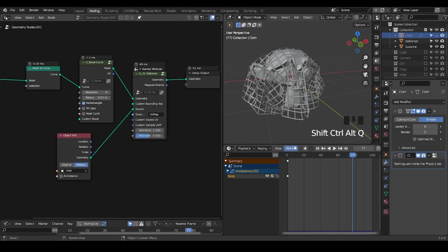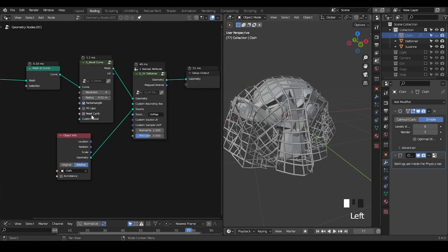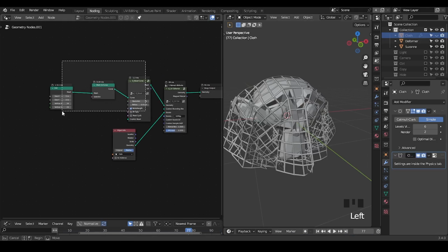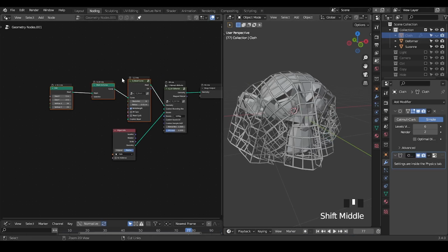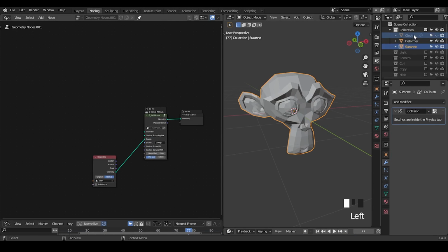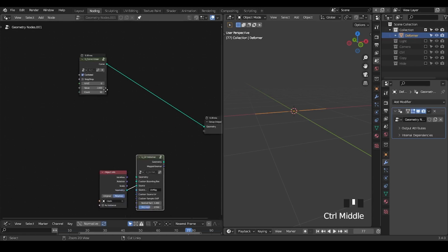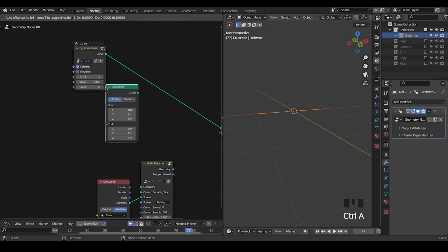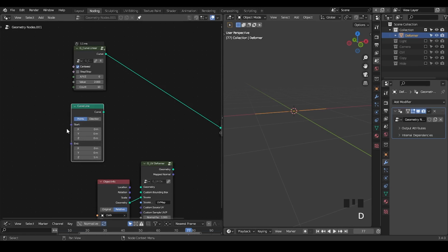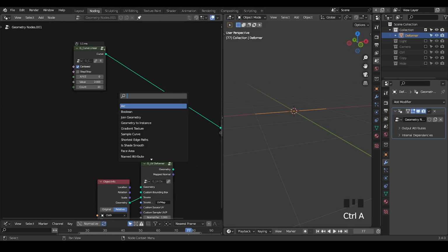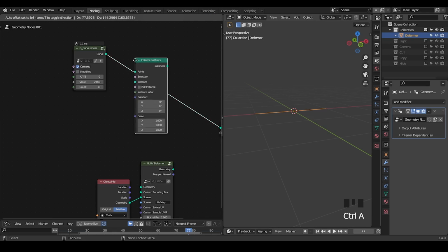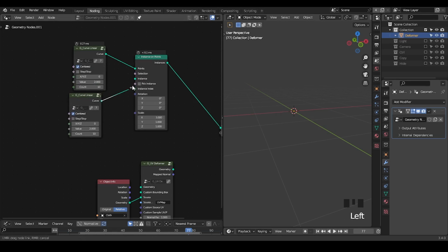So this is just a basic example. We're going to move on with a more complicated example than just the web. Right now, we do not need all this cloth and Suzanne. We're going to create a knitted pattern, which I've discussed in the past. So let's start with a curved linear. A curved linear is basically just a curve line node with resample, so that instead of just a start and end, I have the count in between, so that I can instance on points with another curved linear to create patterns.